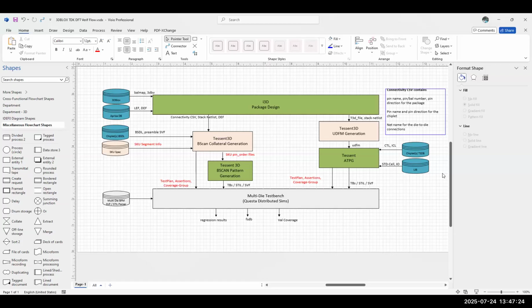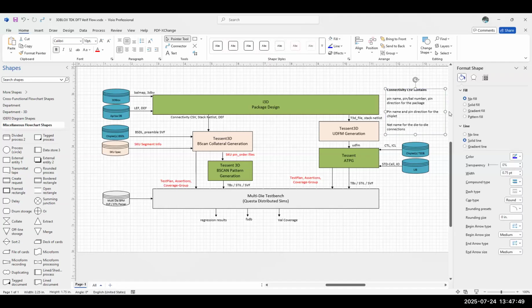Okay, so thinking about that, if it's just XY coordinates and pins, that's already captured as part of each chiplet footprint definition, and then the assembly, right? What goes where. So technically, that information already exists. It exists, but the DFT scripts are not going to be able to read a complex assembly type of thing. It could easily be generated from that assembly stack and die information. Yeah, exactly. The information for that already exists, not necessarily in the format you want.